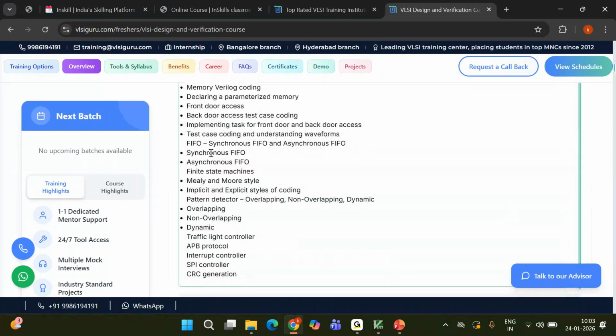Okay. So then understanding a FIFO, first in first out. It's a buffer actually. It's a memory. FIFO is also a memory, but it acts like a buffer between two components when they're working at different frequencies. What is a FIFO? FIFO is a buffer. It's a memory itself. Okay. But where is the FIFO used? FIFO will be used when component 1 wants to communicate with component 2, where these two components are working at two different clock frequencies.